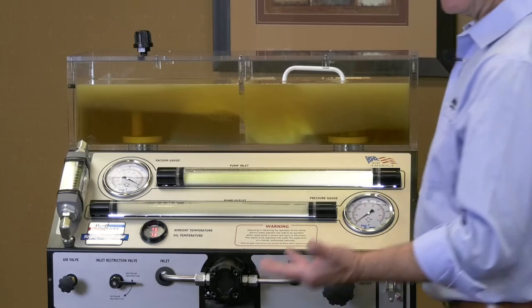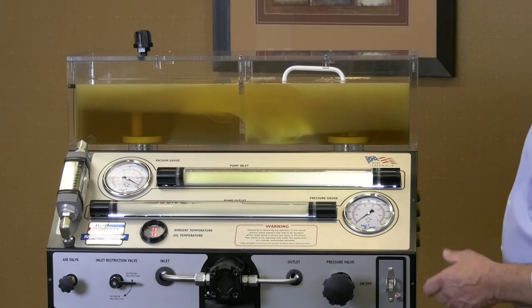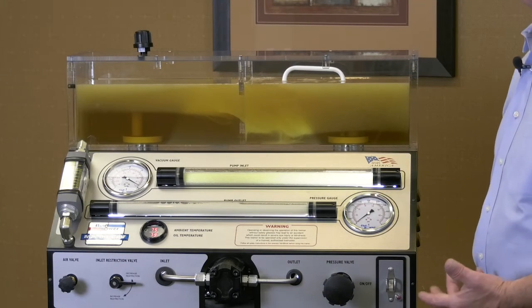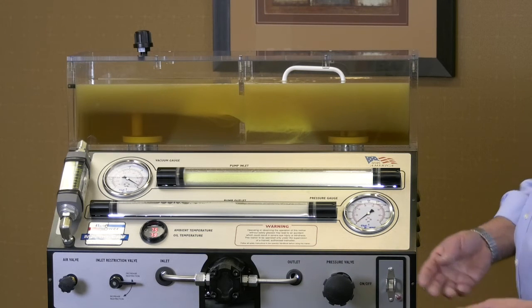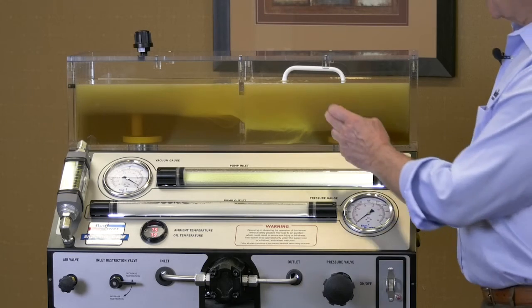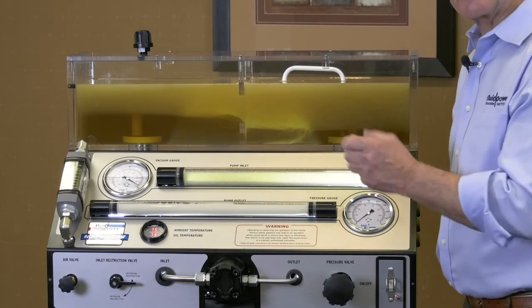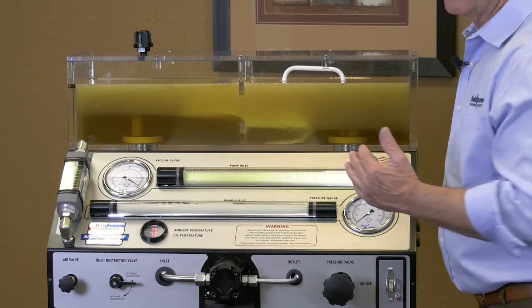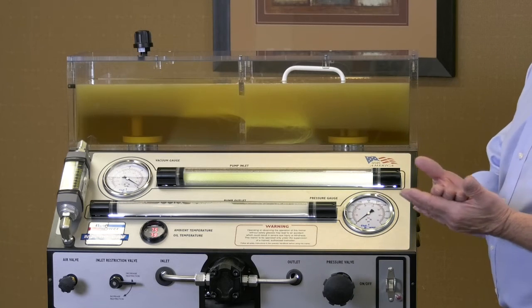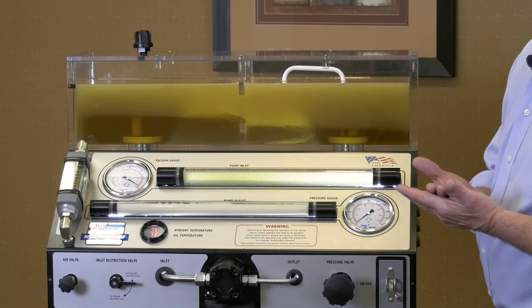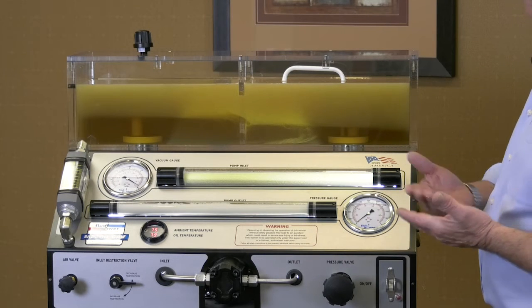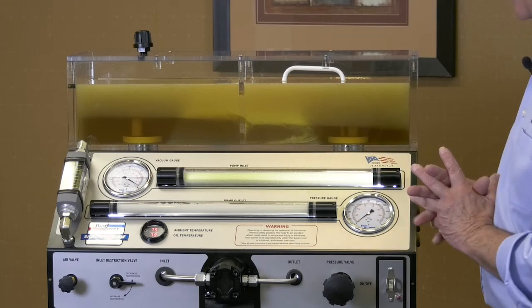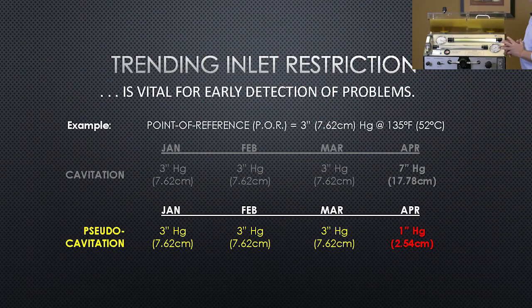I can see a gain in the oil temperature. This condition is called pseudo-cavitation, or if you will, air contamination of the oil. Sometimes when people look in a sight glass and see that the oil has changed its complexion like it has here, we get confused between aeration and water contamination, because water will change the complexion of the oil as well. So this is a catastrophic, systemic condition that needs to be nipped in the bud.